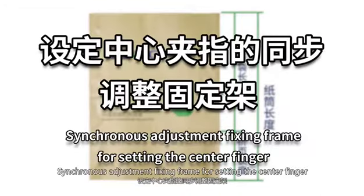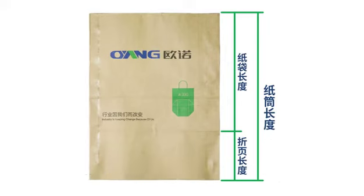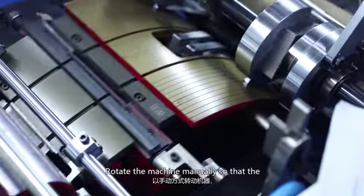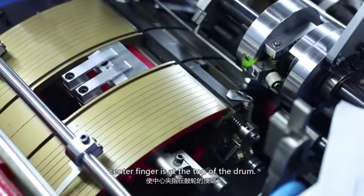Synchronous adjustment fixing frame for setting the center finger. The length of the first fold is calculated by subtracting the length of the paper tube from the length of the paper bag. Write down the length of the first fold as the position for adjusting the center finger. Rotate the machine manually so that the center finger is at the top of the drum.